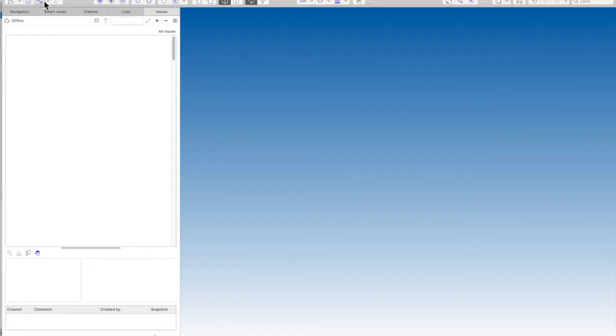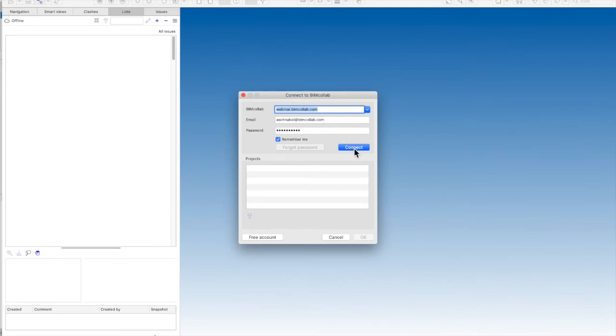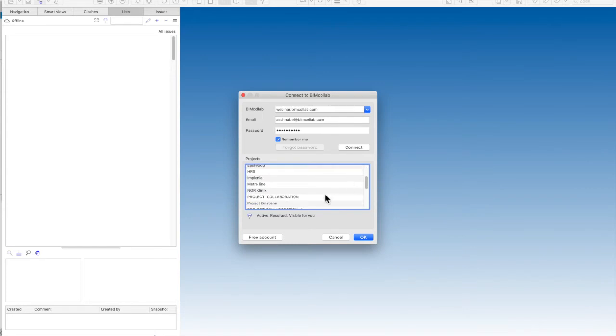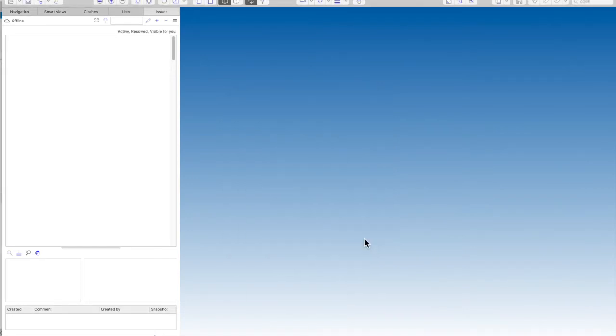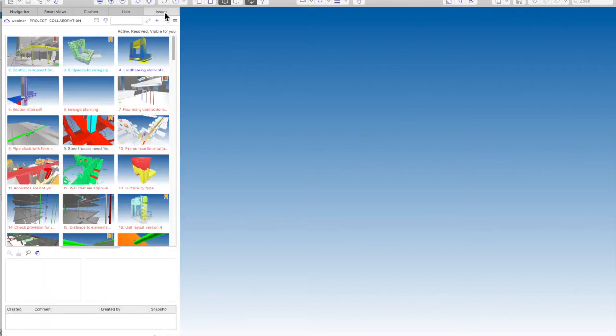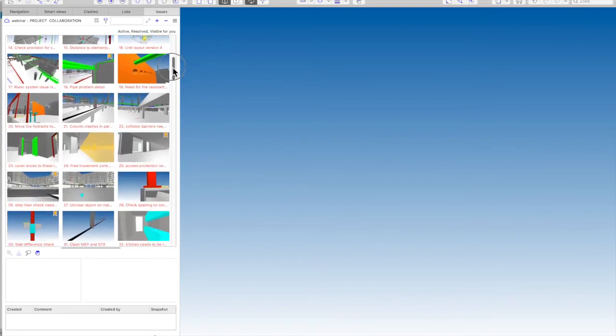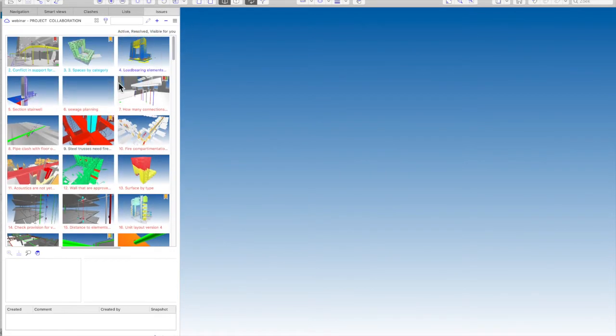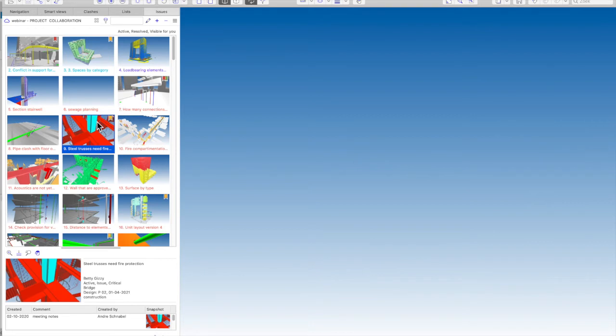coordination. So when we want to participate in BIM coordination, we need a viewer and we need the connection to the information. So in this case, I will log in from BIMcollab Zoom into the BIMcollab space, and I will connect to BIMcollab Cloud. In this case, there is some integration set. First of all, a software that does not block any communication. To have everything directly from a cloud service, centralized, knowing that you have the latest status.